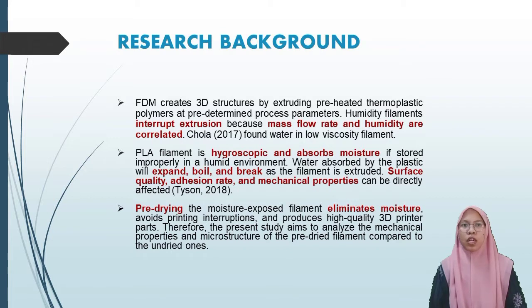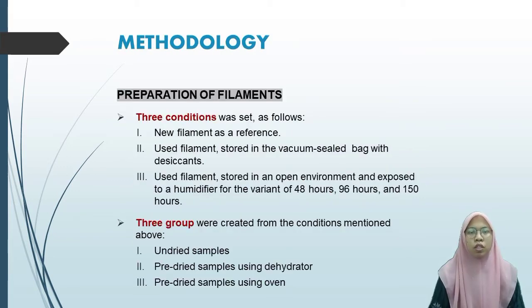Therefore, in this research, our aim is to analyze the mechanical properties and microstructure of the pre-dry filaments compared to the undry filaments. For the methodology, 3 conditions were established in this research. The first condition is new filament as the reference. The second condition is filament stored in a vacuum bag with 50 gram desiccants, and the third condition is filament stored in an open environment and exposed to the humidifier for 48 hours, 96 hours, and 150 hours.